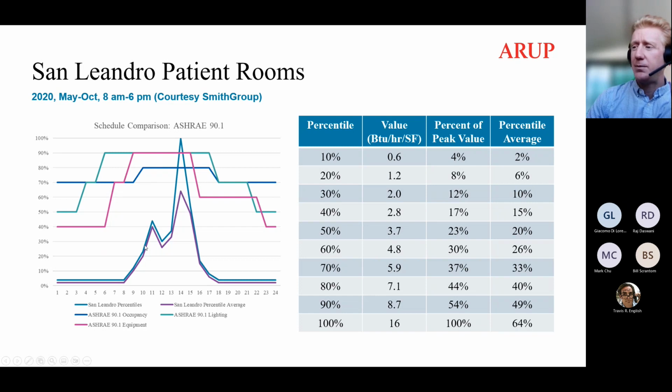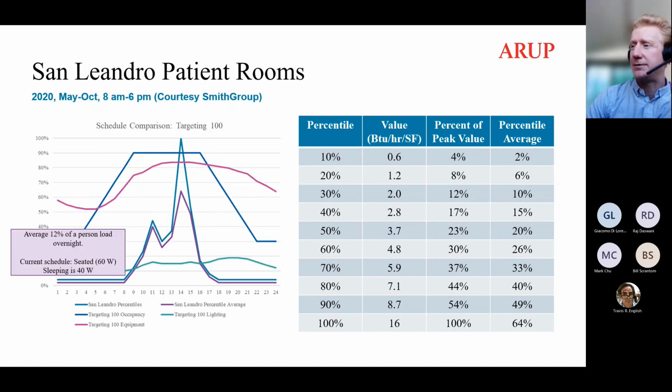And compared to what we see pulling a schedule out of that San Leandro data, it's much, much higher, and we would get a much peakier profile if we tried to replicate and just sort of extract into a similar 24-hour period the values from that San Leandro cooling load data. This is one place already where, in general, the shape sort of matches. We've added here a bit of a dip over the lunchtime period, but that could be moved around within this profile. And even though the general shape matches, the amplitude is quite different, and even the overall shape is not as uniform as we might expect.